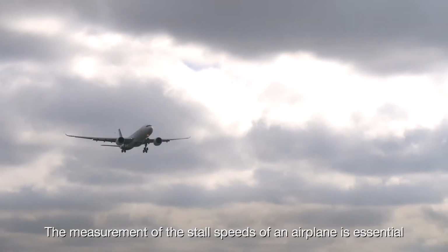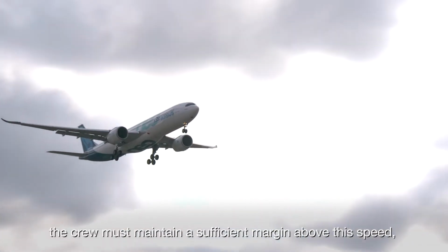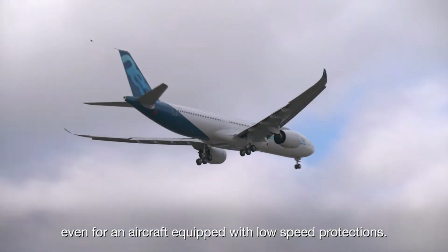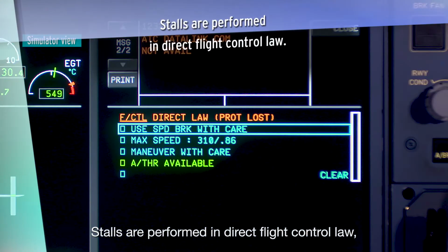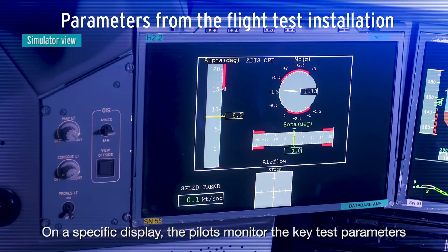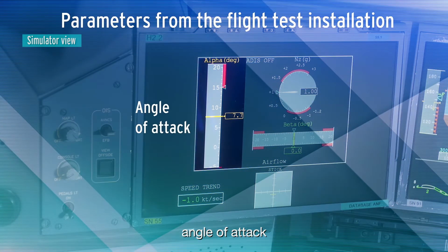The measurement of the stall speeds of an airplane is essential because in all circumstances, the crew must maintain a sufficient margin above this speed, even for an aircraft equipped with low-speed protections. Stalls are performed in direct flight control law, which means that the deflections of the control surfaces are proportional to the deflection of the side stick. On a specific display, the pilots monitor the key test parameters obtained from the flight test installation, angle of attack, and side slip.